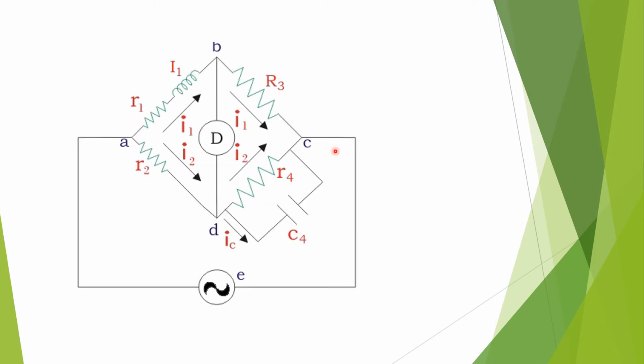So this is the circuit diagram of a Maxwell bridge. So we have R1, L1, the resistors and inductors here, R3, R4 and R2, the four arms of a circuit. An AC bridge consists of a source, a balance detector and four arms. In AC bridges, all four arms contain an impedance. The AC bridges are formed by replacing the DC battery with an AC source. That is why we represent it as here. So these are very highly useful to find the inductance, capacitance, storage factor, dissipation factor and etc.